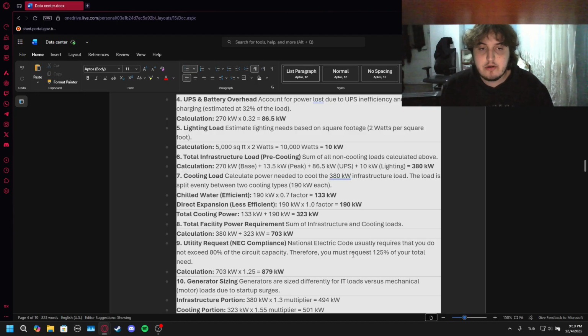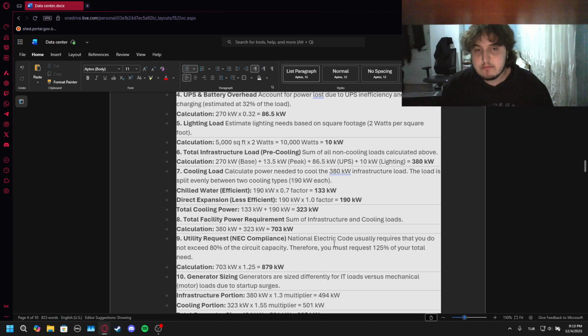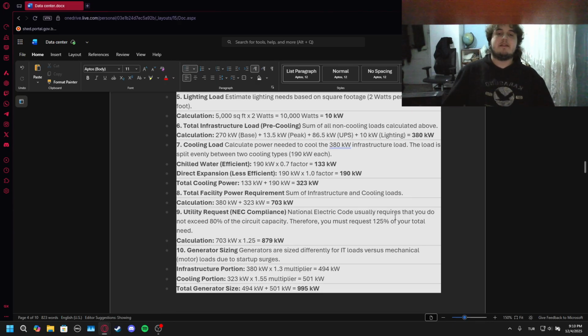Utility request, NEC compliance. The National Electric Code usually requires that you do not exceed 80% of circuit capacity. Therefore, you must request 125% of your total need. Calculation: you put all of this so you don't actually go overboard and destroy everything.